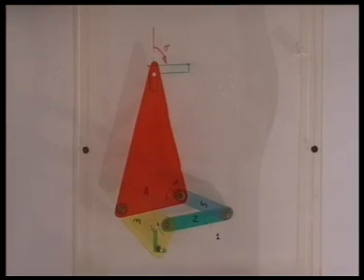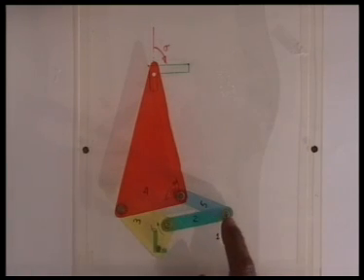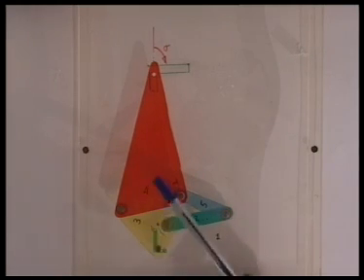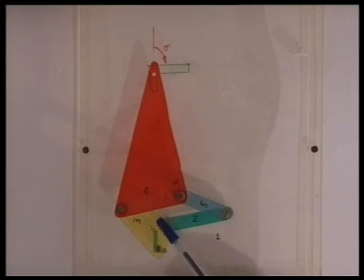As a second example of this kinematic analysis through the link vectors, let us look at the model of this mechanism, which is a copying mechanism or plagiograph. What we see here is that this is a 5 link mechanism, the fixed link, and there are 4 moving links, 2, 3, 4 and 5. And the dimensions of these links are such that this forms a parallelogram. This link length is equal to this link length is equal to this. And these 2 triangles are similar triangles, that is this angle is same as this angle and this angle is also same as this angle.